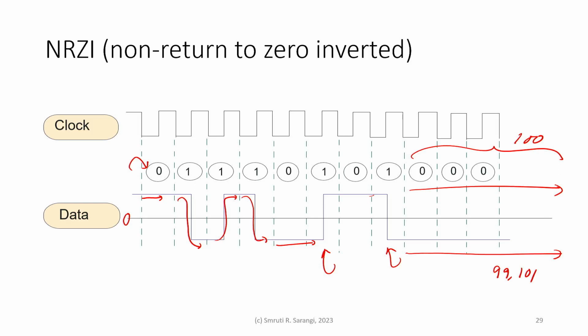It reduces the bandwidth of the channel, but only a little bit. Trust me, you need to introduce a dummy transition where it is known, something that will get filtered out later. A dummy 1 is introduced such that there is at least one transition, so the receiver clock can synchronize itself to it.